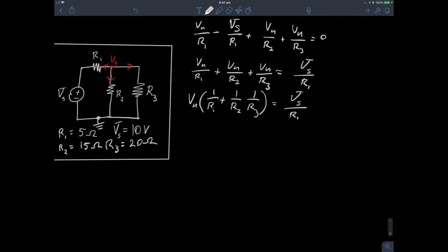Alright. And if there's any point throughout this video you feel like, okay, I know where I'm going now, just pause the video, have a go, and see if you get the same thing as I do. Alright, so now I'm going to divide both sides by that big long bracketed term, and you get Vs on R1 over 1 on R1 plus 1 on R2 plus 1 on R3.